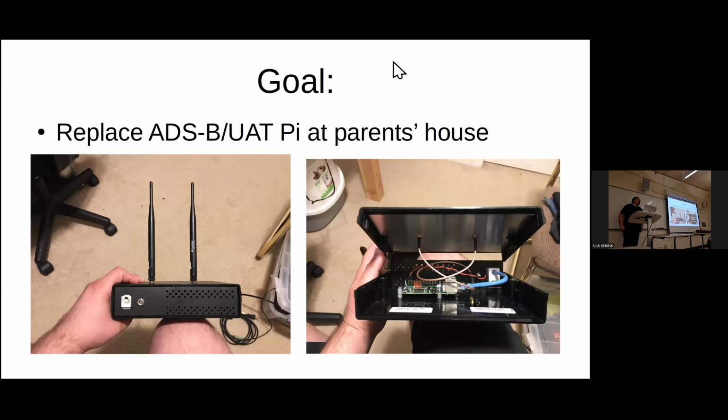It's fun. So I set up this little box with a Raspberry Pi and a couple of SDR receivers at my parents' house, and it worked okay. These little 5 dBi antennas sitting inside performed decently enough. But I thought I would like to do something a little more interesting. I'd like this to perform better. I'd like to maybe listen to a few more things.